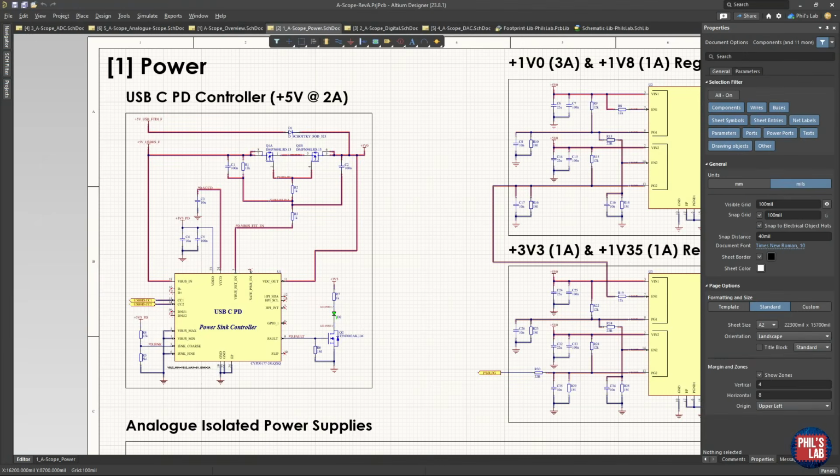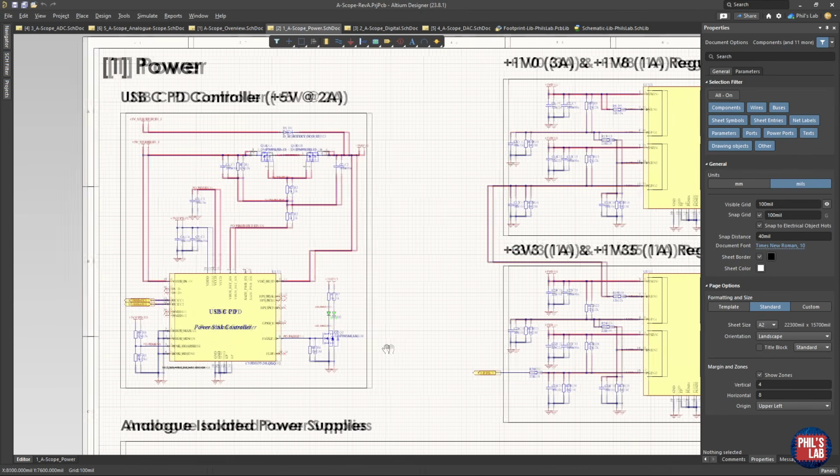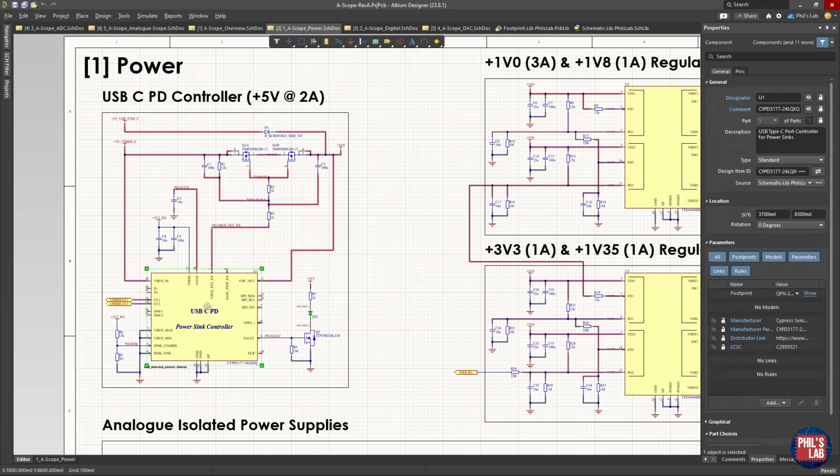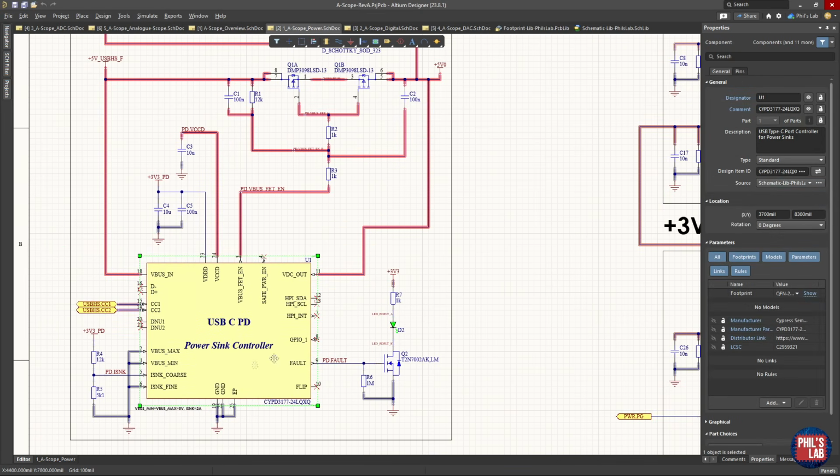Once you've understood datasheets and how to navigate them, how to make informed decisions, and how to choose parts based on datasheets, typical hardware designs can be a lot less daunting because of all the information you can find in datasheets and app notes. For example, for a latest hardware design of mine, all these parts you see here, for example this USB-C power delivery controller, all of these external parts are chosen based on datasheets.